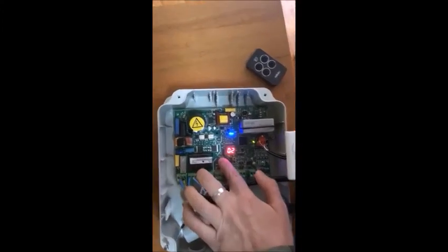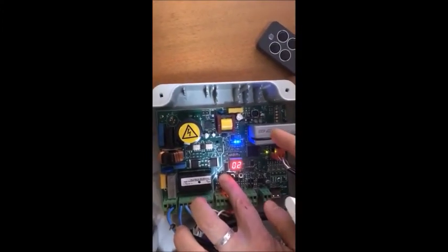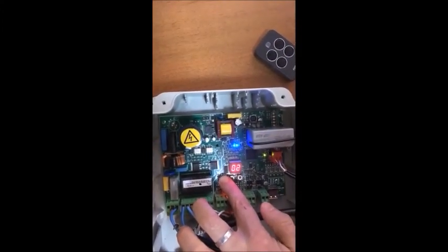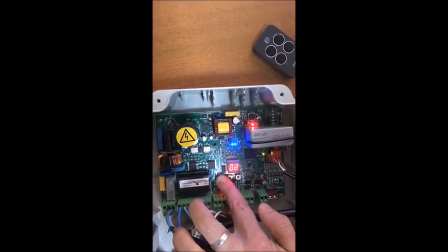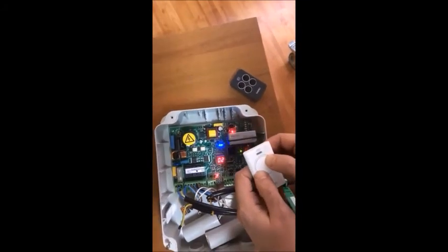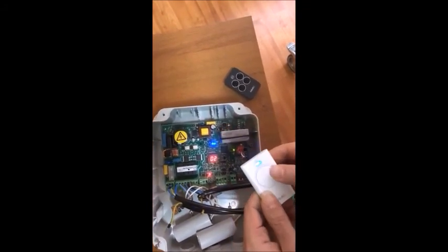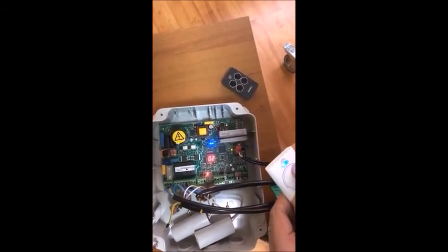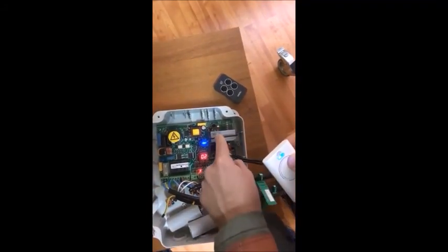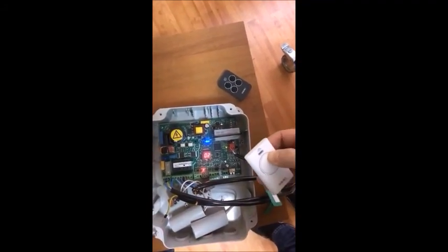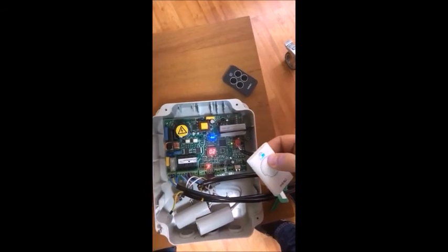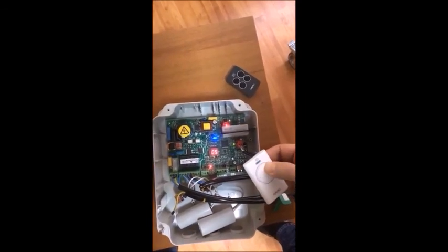To teach your SLH transmitter to the open A function, press and hold the plus button for about 5 seconds until you see the red radio 1 LED start to flash. Put your transmitter into teaching mode by holding 1 and 2 down. Press the button you wish to learn and you'll see the flashing red LED goes solid and extinguishes. And at this point you can release the SLH transmitter and your remote is ready to use on the gate.